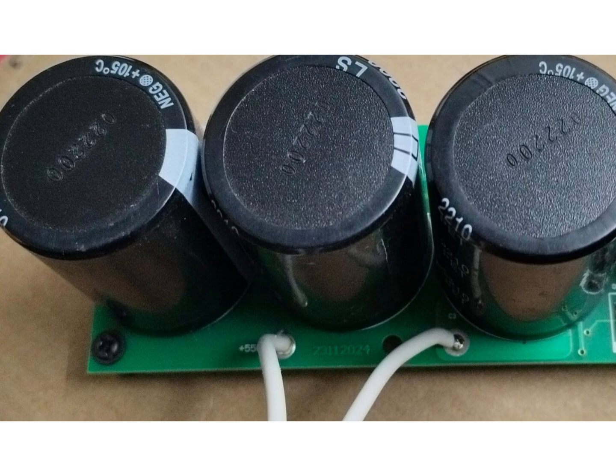The onboard capacitors are mainly high-frequency decoupling capacitors, placed close to the half bridges to handle fast switching currents, while the external electrolytic capacitors provide the required energy storage and low-frequency ripple filtering. This separation of bulk and high-frequency decoupling is a common and effective practice in high-power inverter designs.